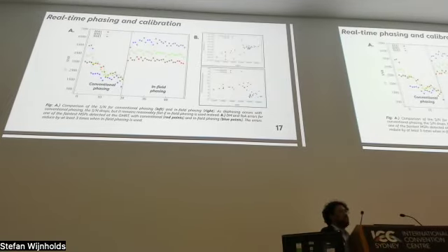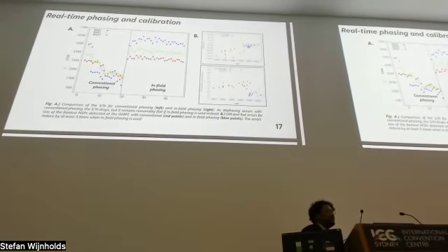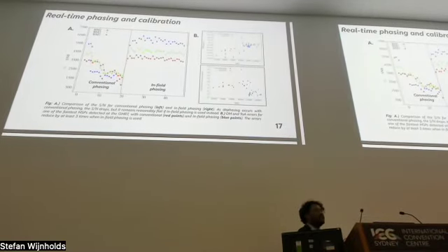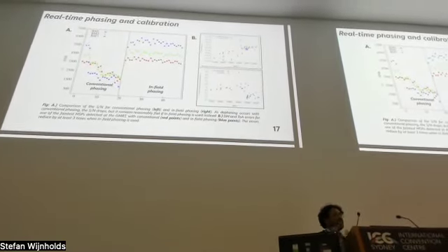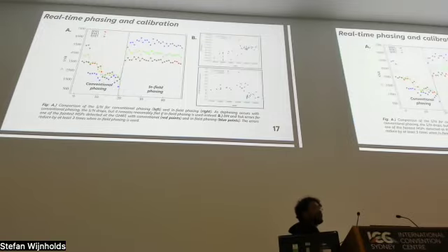And there are some applications where you might require long-term continuous scans. So one solution is infill phasing, or real-time phasing, where we use an already stored model of the sky to do on-the-fly calibration. So the visibilities that are being recorded will be compared with the sky model. It's kind of like a self-calibration, but just done in real time in the system.